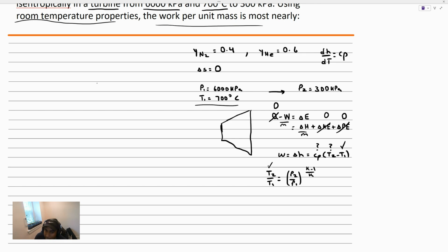What about Cp? So I'm giving you some intuition here for how we find intensive properties of mixtures for ideal gases. If we were looking at the enthalpy of the mixture, we can sum the enthalpy of the first component and the enthalpy of the second component if we had a two-component mixture. If we look at the specific enthalpy, so we take the mass of the mixture multiplied by the specific enthalpy of that mixture, that's equal to the mass of the first component times the specific enthalpy of the first component plus the same thing for the second component.